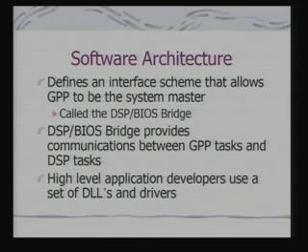So, the software architecture for OMAP defines an interface scheme that allows the general purpose processor to be the system manager. This interface scheme is called DSP BIOS Bridge. And this DSP BIOS Bridge provides communication between GPP tasks and DSP tasks.